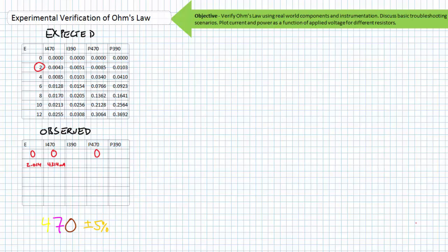If at any time I noticed an extreme deviation between the two, I would have immediately stopped and rectified the situation before continuing. Imagine if I had a 47 kilo ohm resistor instead of a 470 ohm resistor because of an errant reading of the third band inside the 4-band color code. In either case, my current would have been a power of 10 different. This is a cause for immediate concern. Be sufficiently aware to recognize this event and shut her down till you fix it.